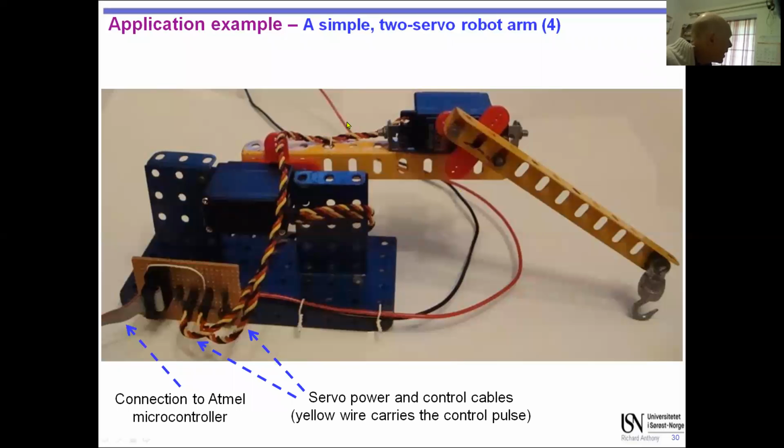Obviously, here I've got a little extra board that takes these signals and patches them on, because the microcontroller I used had both the wiring on the port. It was all based on these 10-bit connectors, so I couldn't plug these straight on. What you would probably do is take your servo connector and plug 3 jumper wires into the end and connect them directly on the servo port. It is probably the easiest way, or onto your breadboards probably, and then onto the servo port is probably a safer way to do it.